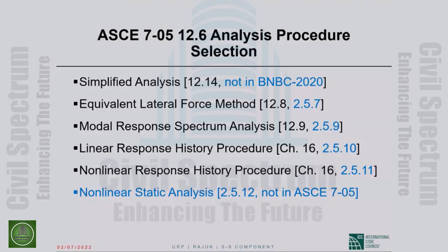Modal response spectrum analysis, I will do that next Monday. 12.9 of ASCE 7, 2.5.9 of BNBC. Then there are linear response history and non-linear response history procedures. I will not go there.